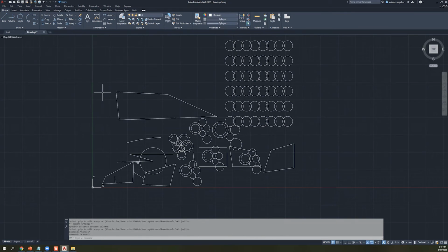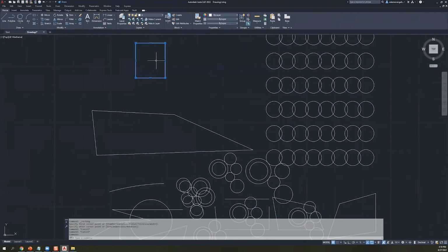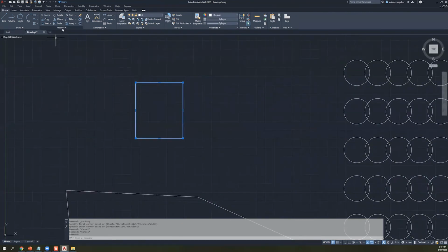And another fun trick about this all as well is that if I draw a square like this, and I have a selection on it, you can actually get to a lot of these modify commands by clicking on one of these pick points like this, right? And by default, it's already kind of moving it in a sense. And if you press spacebar while having one of these highlighted, it'll actually transition to the next option. This is move, for example, using that as a base point.